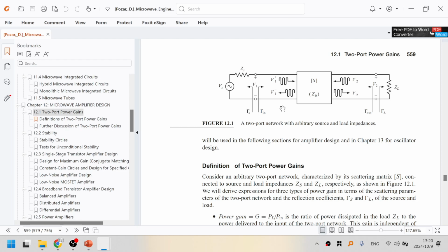But in a later session, you will see that there is a trade-off between the noise figure and the maximum available power gain. But you can see the overall process, the key component is the source impedance. This is actually an arbitrary value we are choosing, and we are hoping that this impedance will maximize the gain and lower the noise figure. Another important chart in designing these amplifiers is the contour plots over the Smith chart describing the noise figure and the gain, and we can show this process later.